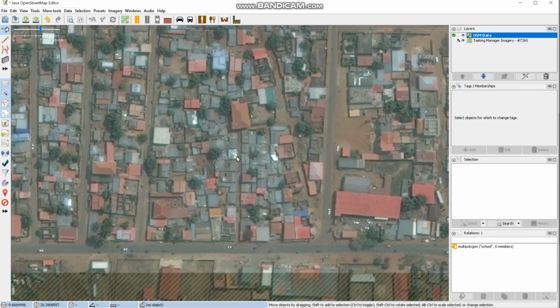We assume that you have the building tool plugin and also the utils plugin as well. And you'll see here you have the building button. The shortcut is B to draw a building. But you could just click this button, draw one corner, two corners, extend, and finish your building.